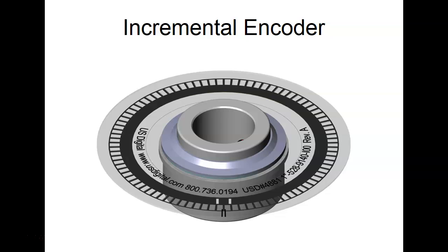Now, what usually happens on your printer when you turn it on? Well, what it's doing is establishing the zero. So what it does, it'll seek over to the left-hand side, and then it finds itself. So what we have to do with incremental encoders is start them from a known position.